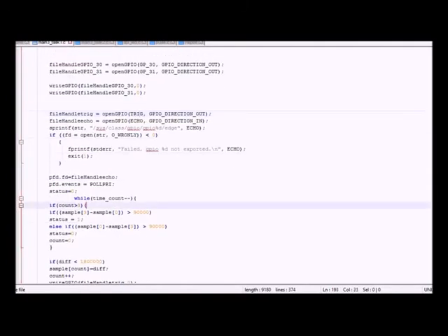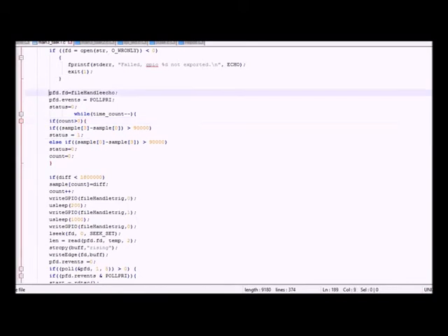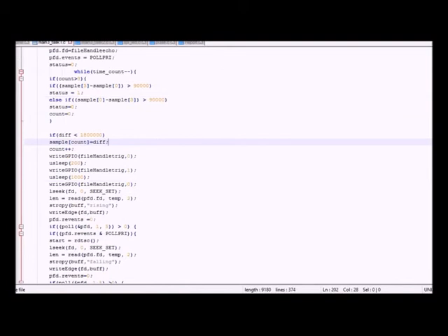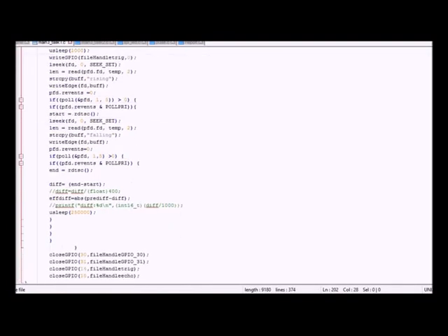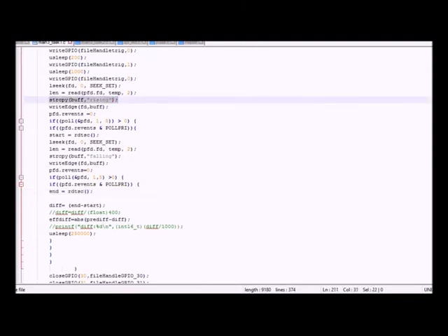So we use the poll function to poll on the echo pin, to detect the rising and falling edges, and we calculate the time difference using the RDTSC, which you could see here. Once we start polling on rising edge, and after you receive a rising edge, you start recording the RDTSC value to get the start value where the edge has risen, and then you start polling for the falling edge.